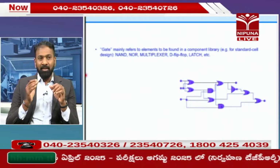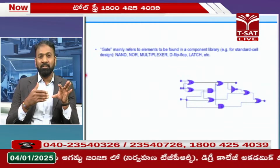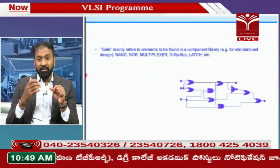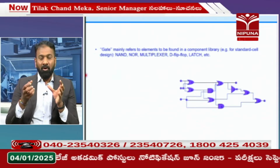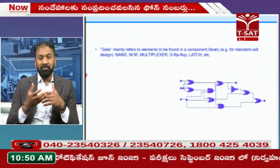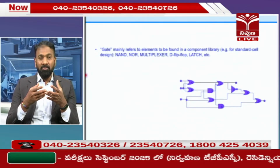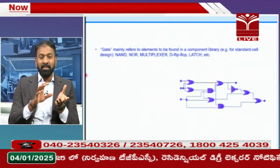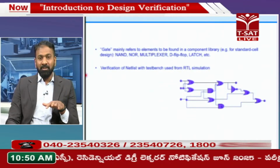The thing is, whenever we rely on tools to convert from the higher level language to some gates or netlists, how can I ensure that it is doing the same job? Any tool can have issues, or maybe the libraries which we are using to model the netlist can have issues. So if you want to do some sort of testing, you have to do a verification at every stage whenever there is a data progression or the design changes. So in this case, I am going to do a gate level simulation as well.